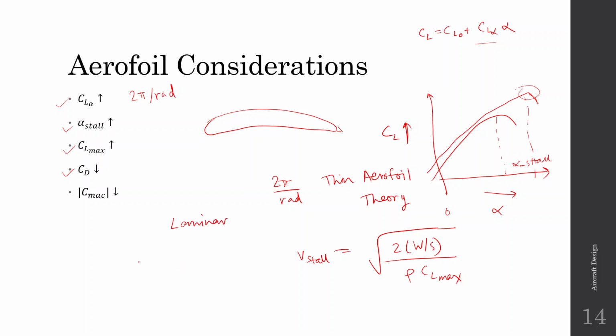He said that a normal aerofoil has a CL-CD curve like this, but a laminar aerofoil is a special kind of aerofoil where, for certain values of CL, your CD is even lower, and there is a region of CL where CD does not practically change.